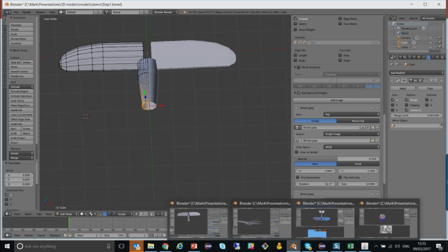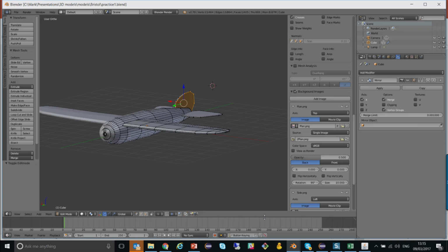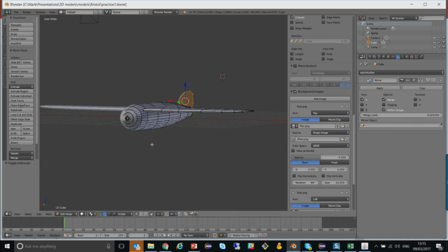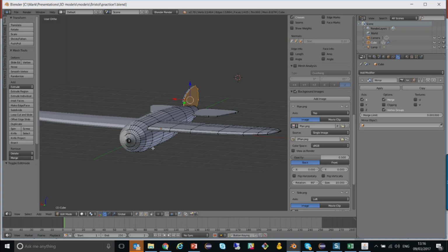I'm just going to move over to one that I've been working on separately. So in this diagram here, I've been extruding the model out towards the front, and I've taken it all the way to the back, and I've actually been using the different parts of the tail plane and drawing around those and extruding those out just a little bit, so that I've got the tail plane. So that's starting to come together quite nicely. The bulk of the aircraft won't take you long to draw. It's the small things like the wheels, the axle for the wheels, and cutting a hole in the fuselage. I'm not going to do that because obviously that's going to take you a very long time.